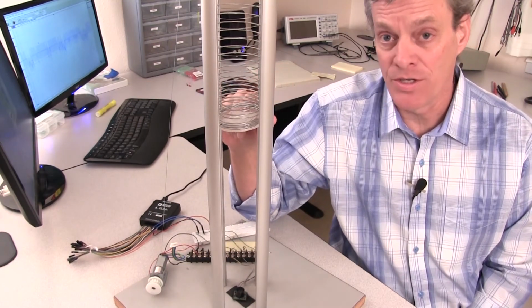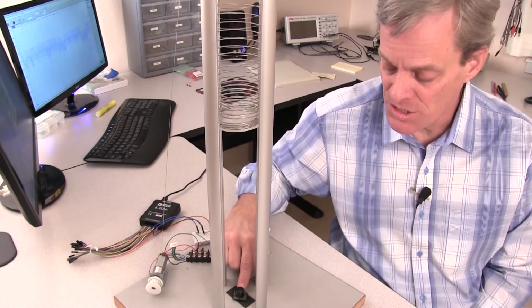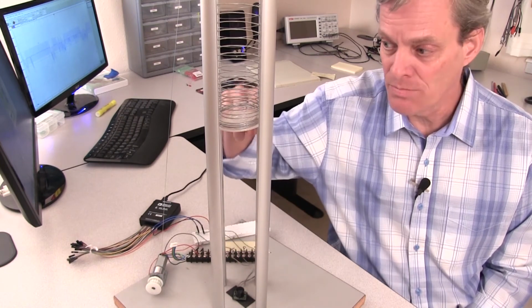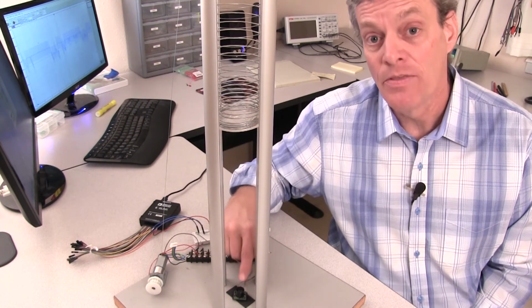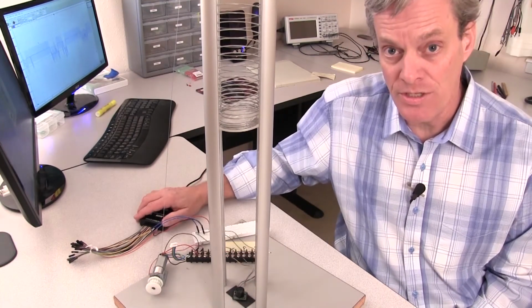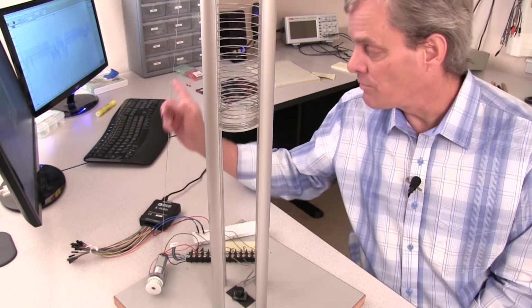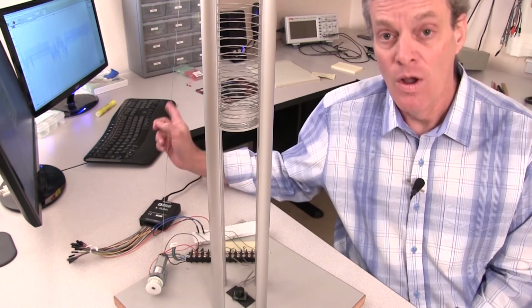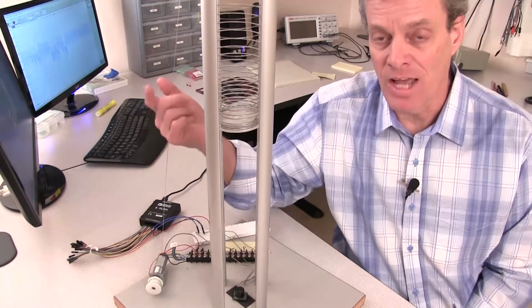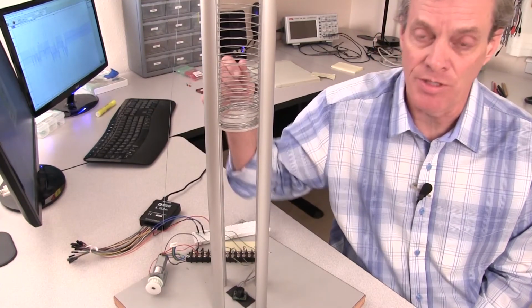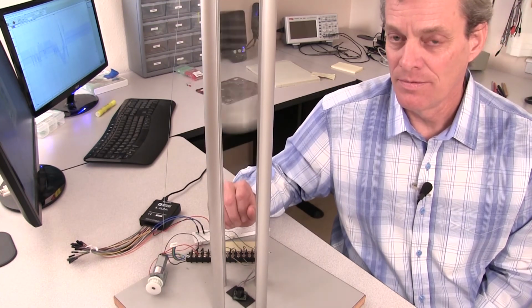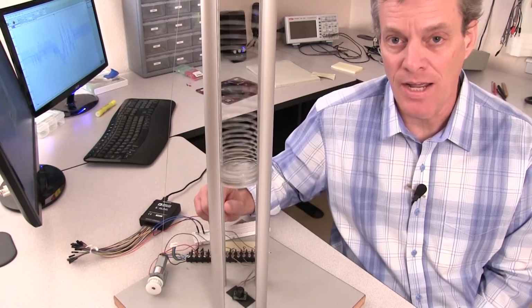I don't have a way to measure its velocity, but I can measure its position with this acoustic proximity sensor. This sensor emits an ultrasonic signal which bounces off the platform and returns. The travel time round trip is converted to a voltage, which I'm recording using a USB-based oscilloscope, which is then recorded onto the hard drive of my computer. Once it's there, I can differentiate the position information to get the velocity, and I'll have completely characterized the system's response. So I'm going to displace this and release it and record the position as a function of time.